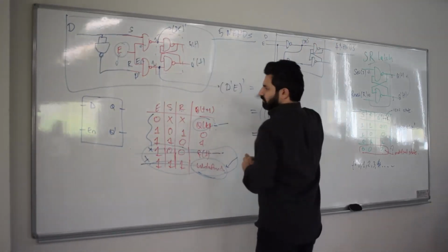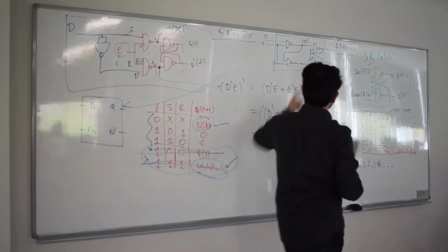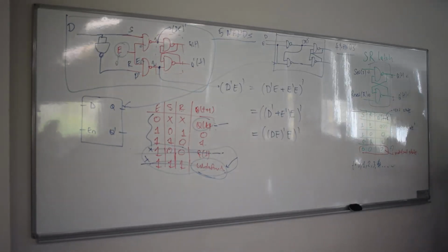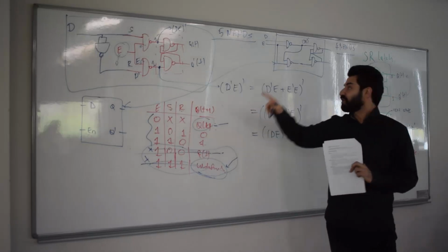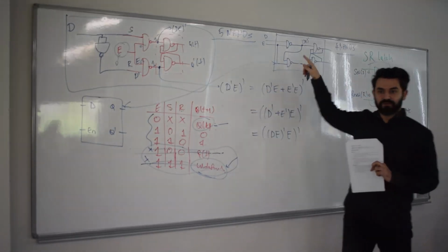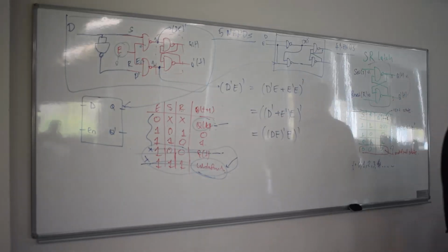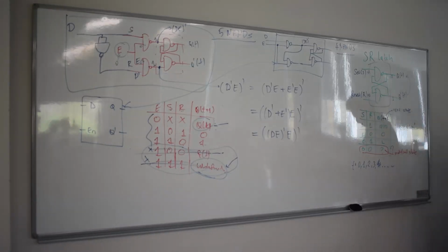Alright? This is what is inside. You see, you can use fewer NAND gates through this simple optimization. Now, every single D latch uses 4 NAND gates. Just keep that in mind, because in the future we probably have to touch upon this several times. And then we can, of course, compare the complexity based on that.